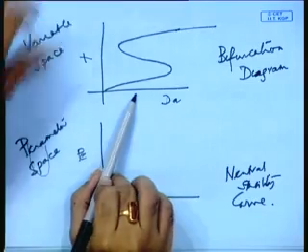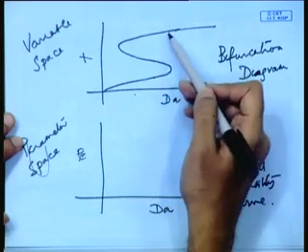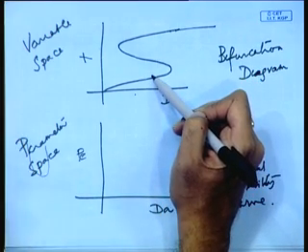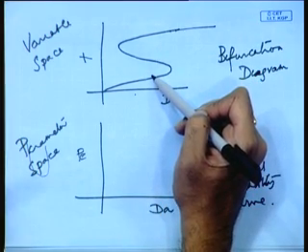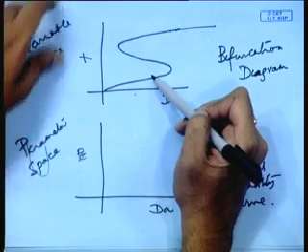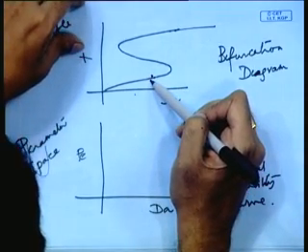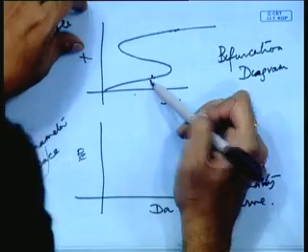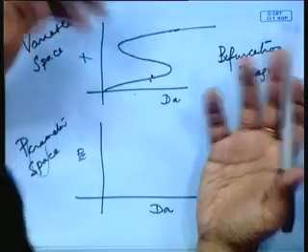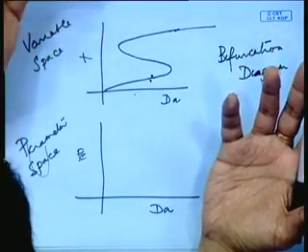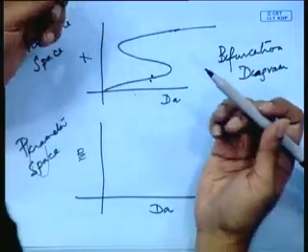That is an important question, by the way. If you look at this bifurcation diagram over here, this is the ignited branch and this is the extinguished branch. It is important to figure out whether the system is going to operate in the ignited branch or the extinguished branch. Why? Because you want it to operate in the ignited branch, because you want product. You won't run a reactor without generating product. So if you are in the extinguished branch, you hardly generate any product.